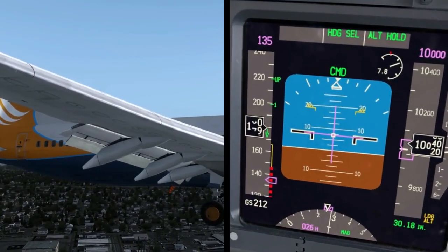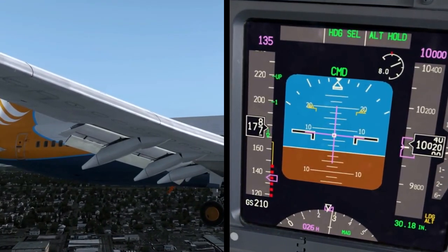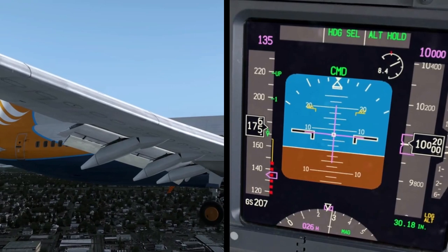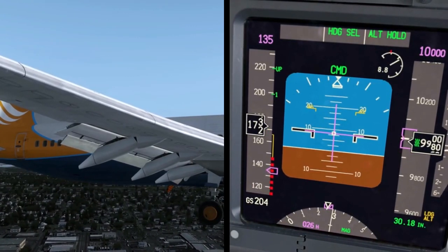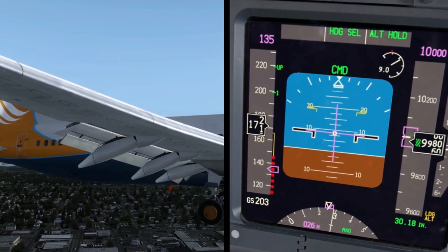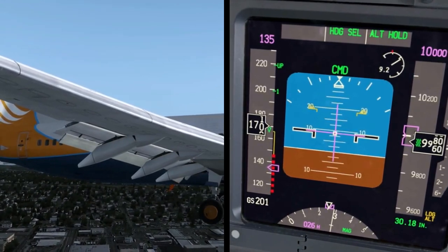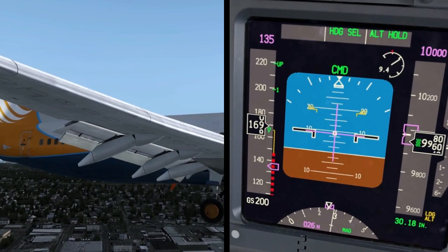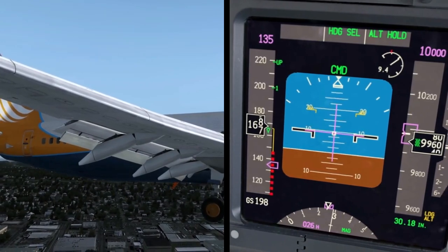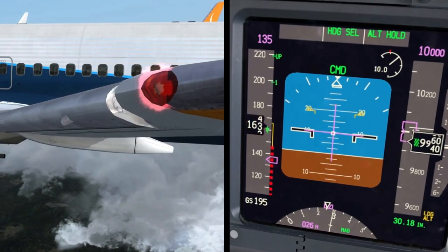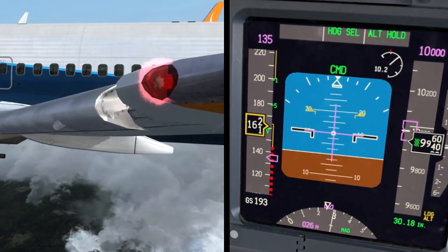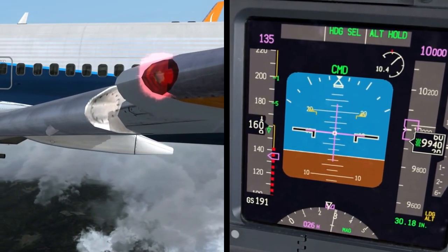Leading edge auto slat function. The auto slat function moves leading edge flaps to the fully extended position when the system senses that the aircraft is approaching a stall condition. Auto slat operation is powered by the hydraulic system B, but an alternate source of power is also provided through the Hydraulic Power Transfer Unit, or PTU. This feature is comprehensively described in the hydraulics lesson.